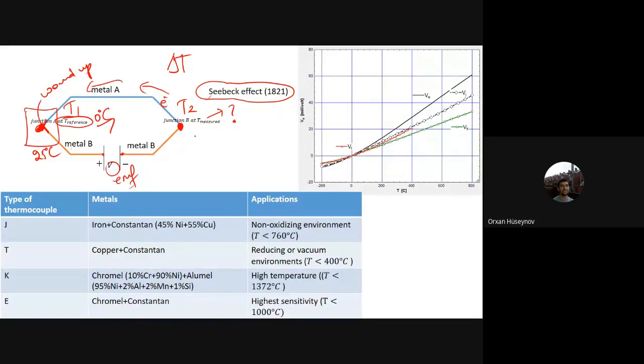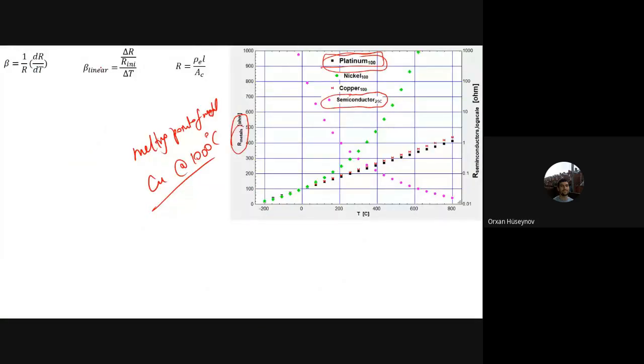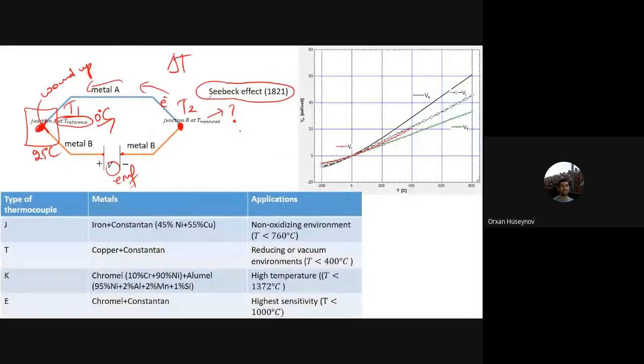Another thing here is that, if you remember from these coefficients, similarly here the voltage change with respect to the initial voltage, this one is voltage, not volume, is again proportional to the temperature change in a linear manner. The temperature change causes voltage change, more temperature change causes more voltage change, but in a linear manner.